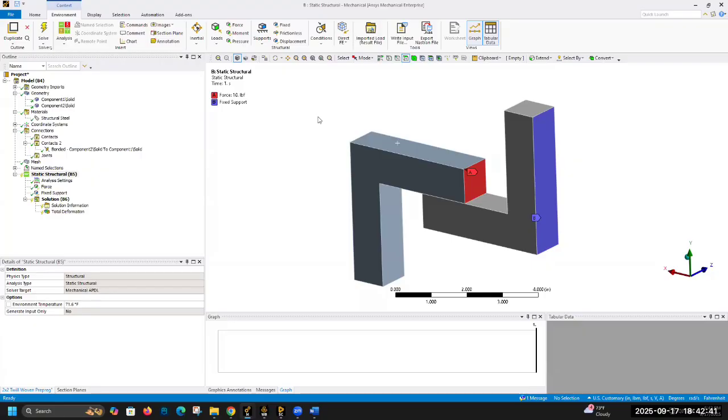Yeah, no, definitely a lot. Anything can be wrong in your model. It could be that you define a material property in PSI when you actually need to define it in Pascals. The reason I'm trying to do more hand calcs too, even though it's harder with more complicated problems, which we'll get into later, is that hand calcs really let you ground it. So even if you have like 15% error with a hand calc, the important thing is that you're within reason.